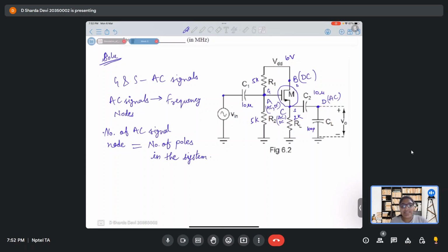So you understand the pole zero system, right? There are poles, there are zeros. In signals and systems, a pole is where your denominator goes to 0 and a zero is where your numerator goes to 0 in a transfer function. You understand that? Yes, ma'am. So your frequency response, which is gain versus frequency, is not always straight. It goes straight, then it comes down. And why does it come down? This is because of poles.